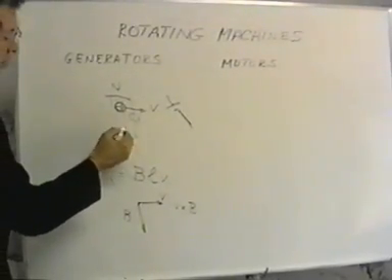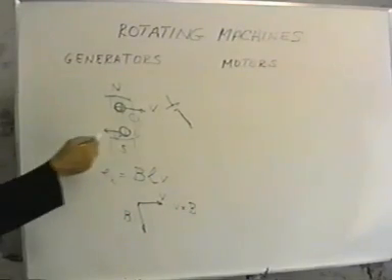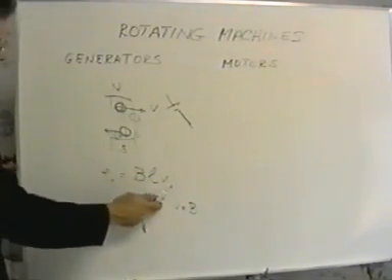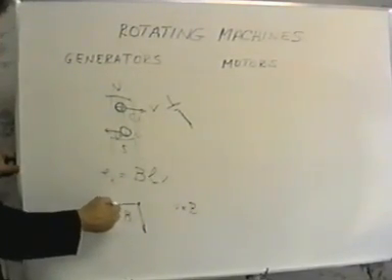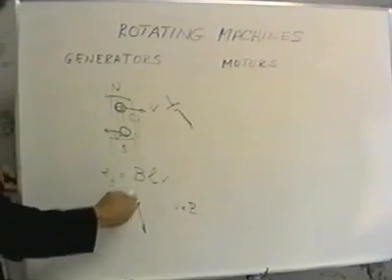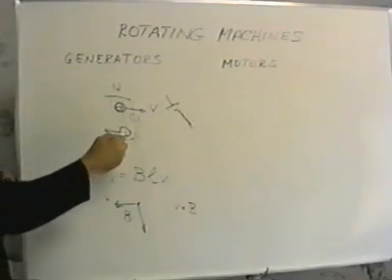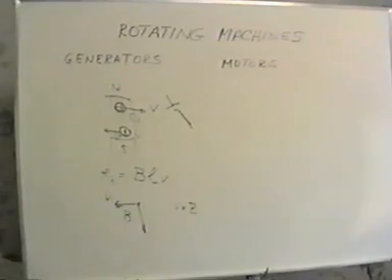Now, if I'm moving in this direction, let's imagine I'm going from right to left, I'll get a voltage induced with the opposite polarity, because what I've just done is reverse the polarity of this v vector like this. And so when I cross v into B, it's coming out from the board. So I'd show the head, or the tip of the arrow, coming out this way.